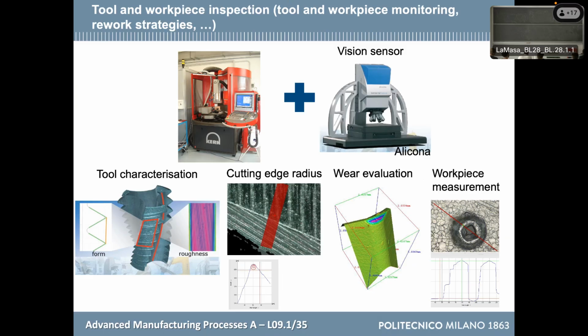This is a cutting edge of a mill. You see striations because, you know, when you produce a mill, you use grinding. So those surfaces are ground. So the edge comes out as just the intersection of two ground planes. In many cases, the tool manufacturers do not have nice control of the rounding, but we know that it is important for us. In fact, the most advanced tool manufacturers apply a treatment here in order to make it smooth and constant.